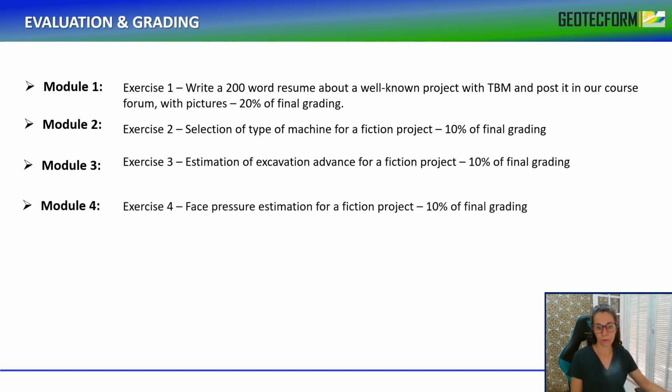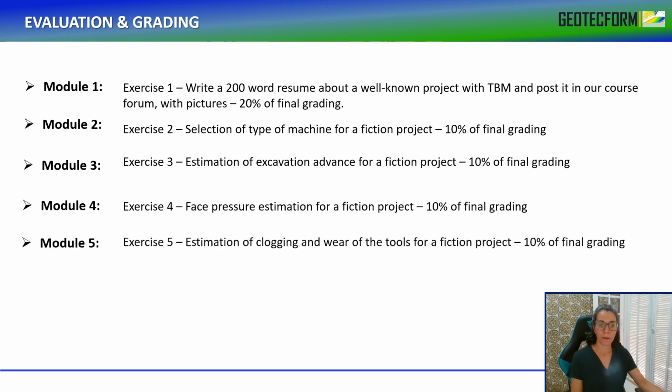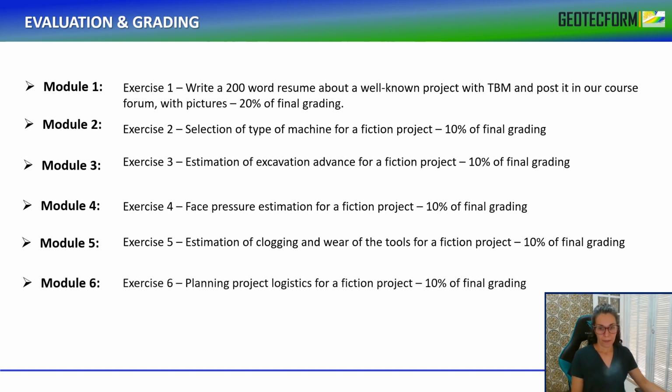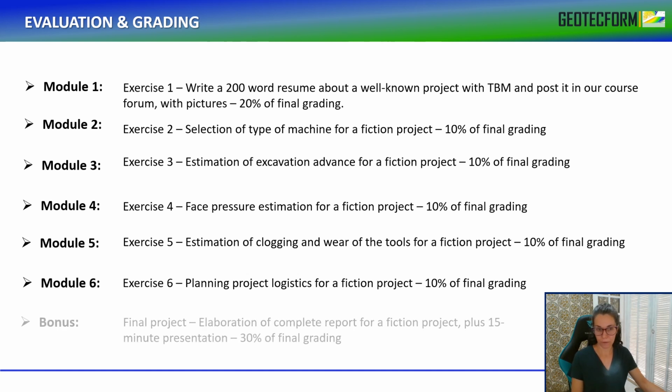Then we're going to look into face pressure estimation, so what are my expected pressures. Then also the estimation of clogging potential: is clogging going to occur or not, and where am I going to have problems. And then we're going to look into the planning and logistics of this final project.